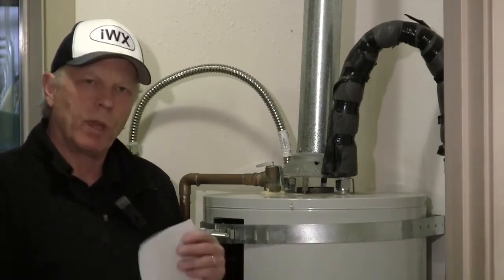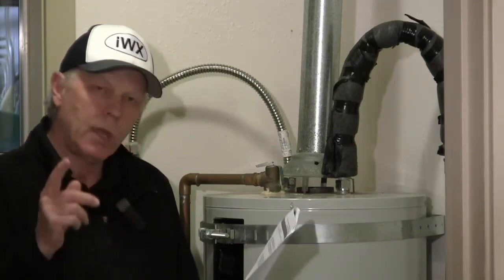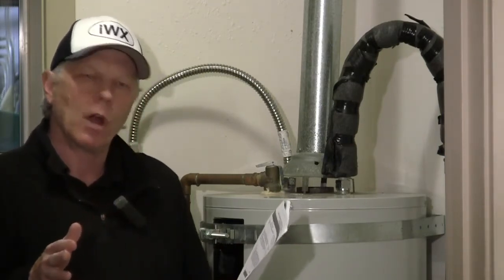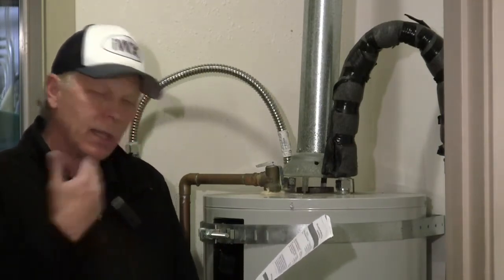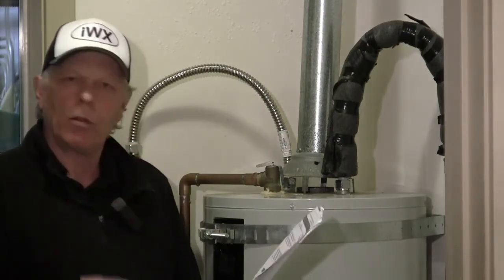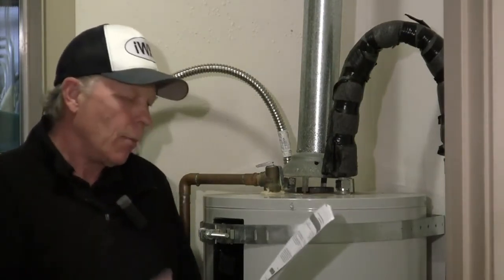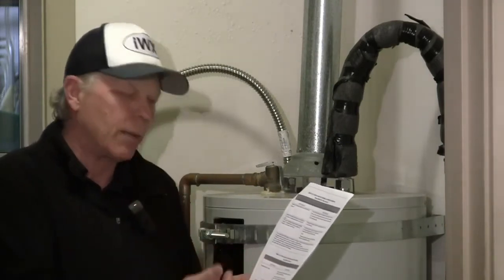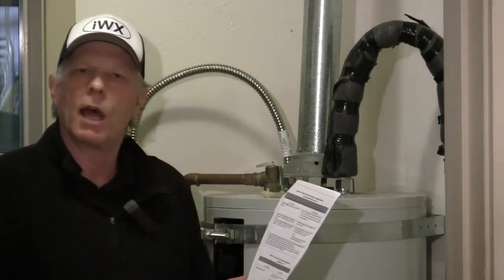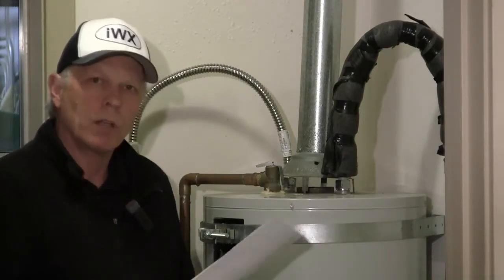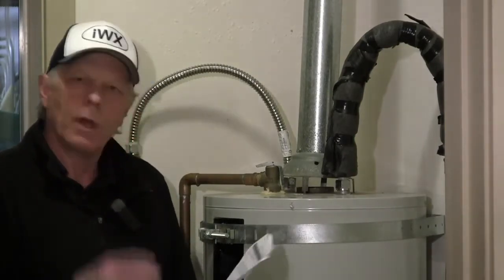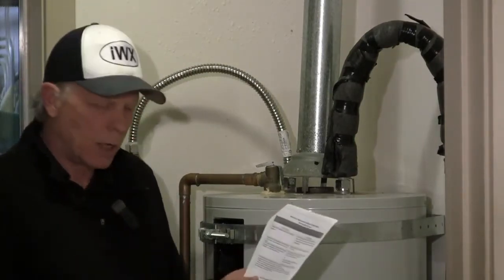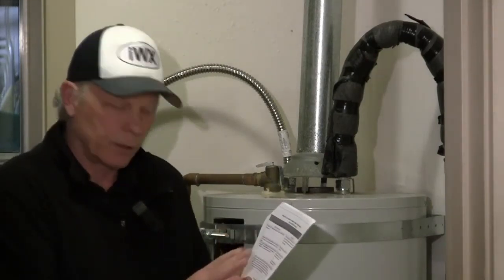Also, you need to be familiar with Table D1B, which is action levels for carbon monoxide. In this case, we had an acceptable level and there would be no action required, but in the cases of unacceptable, that test result is here and the action levels are right next to it. So if you had an unacceptable level, you just read what's on the document here of what to do in that case. Again, you need to be familiar with this document for the test.